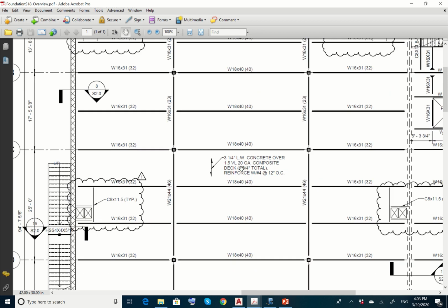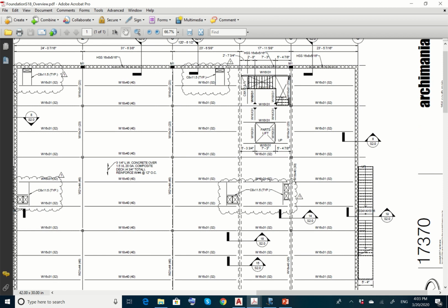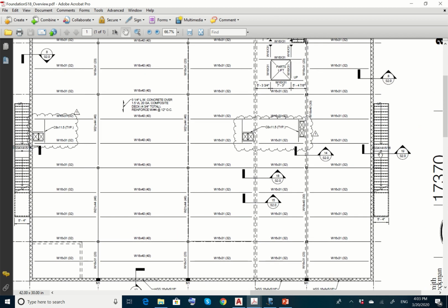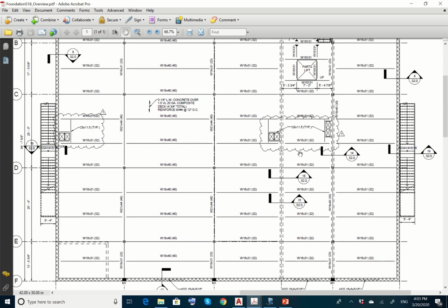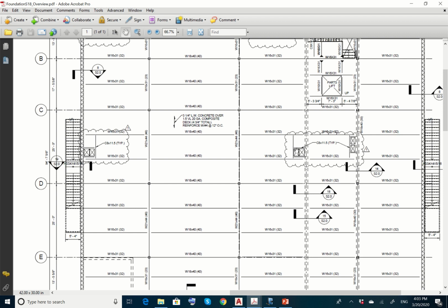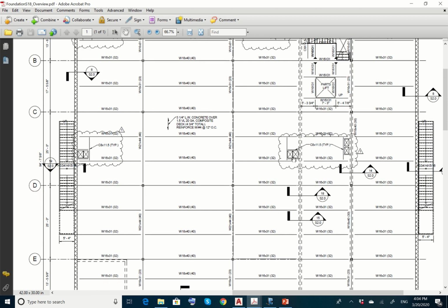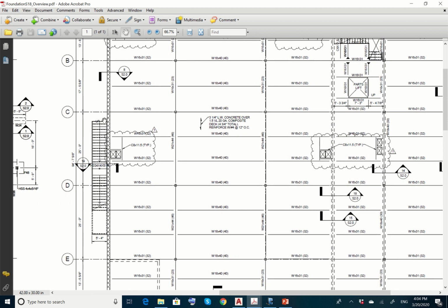So you're going to be drawing all the beams, the concrete masonry unit over here surrounding the building. You're going to be drawing the stairs over here. Okay, the section indications. Here there are some openings, so this is an opening surrounded with those beams. The section for the beams surrounding this opening is C8 by 11.5. This is a channel section, a steel section that looks like a C. And then there are the stairs on this side.